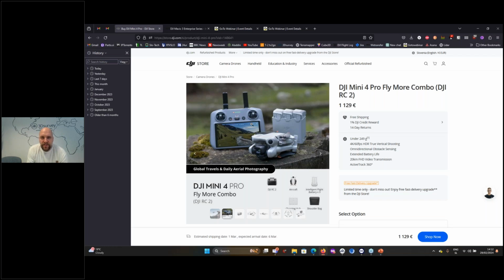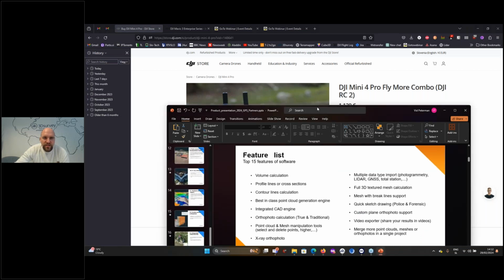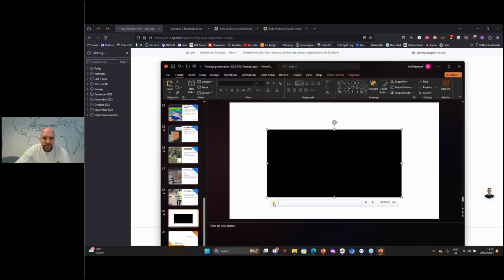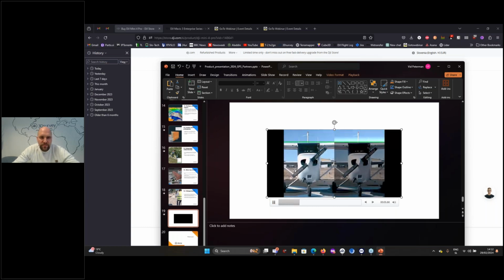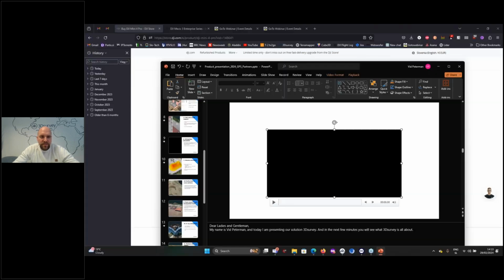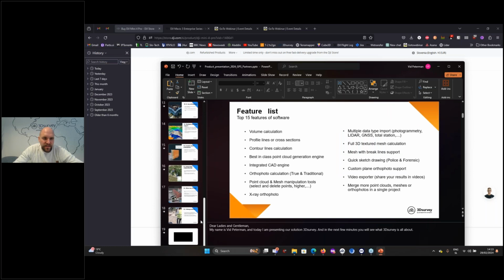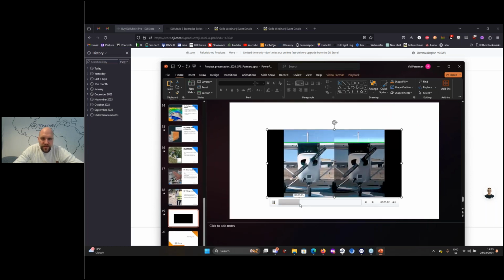The downsides are it has a rolling shutter camera. That means when an image is recorded, it's recorded line by line. And when the image is recorded, it creates a special kind of distortion. I have here a video in which I can show this distortion. So I think you saw this kind of pictures before. This is the result of video being recorded a line at a time. Here on the left, you see a global shutter image, and on the right, this is a rolling shutter image.